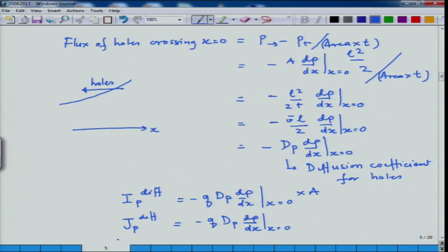So, this is the expression we wanted. We wanted to figure out, due to diffusion in a semiconductor, what would be the net motion of carriers, which would lead to a diffusion current over here. Now, there is a little bit more generalization which is required. I took this example for looking at the motion of carriers at the boundary x equal to 0, mainly for convenience. I could have taken x equal to some value x1 and still I would get the same expression.